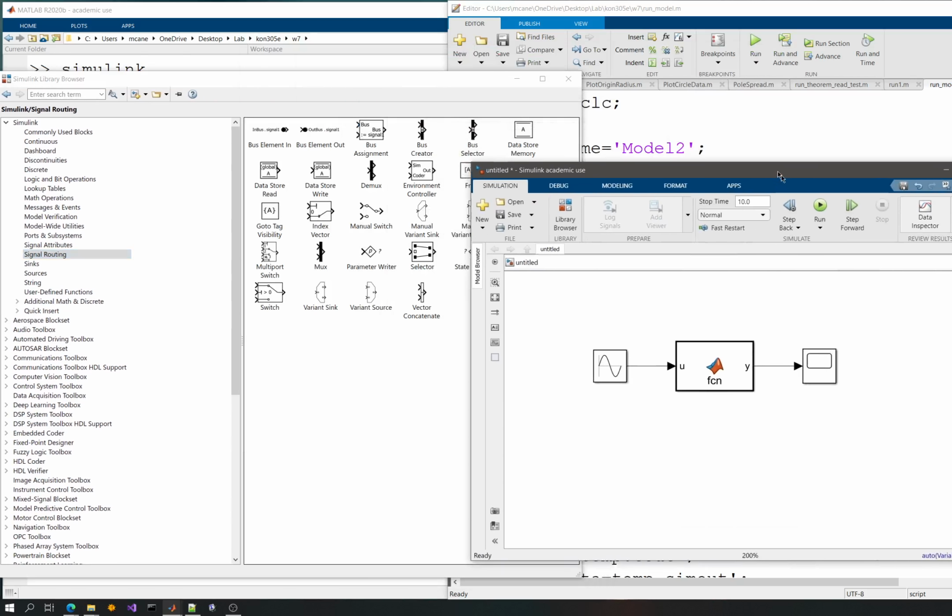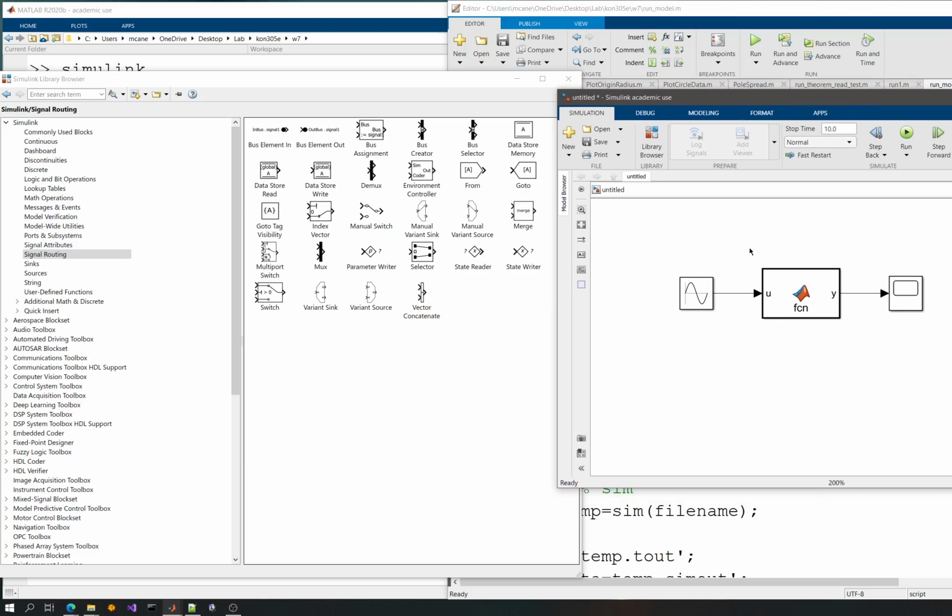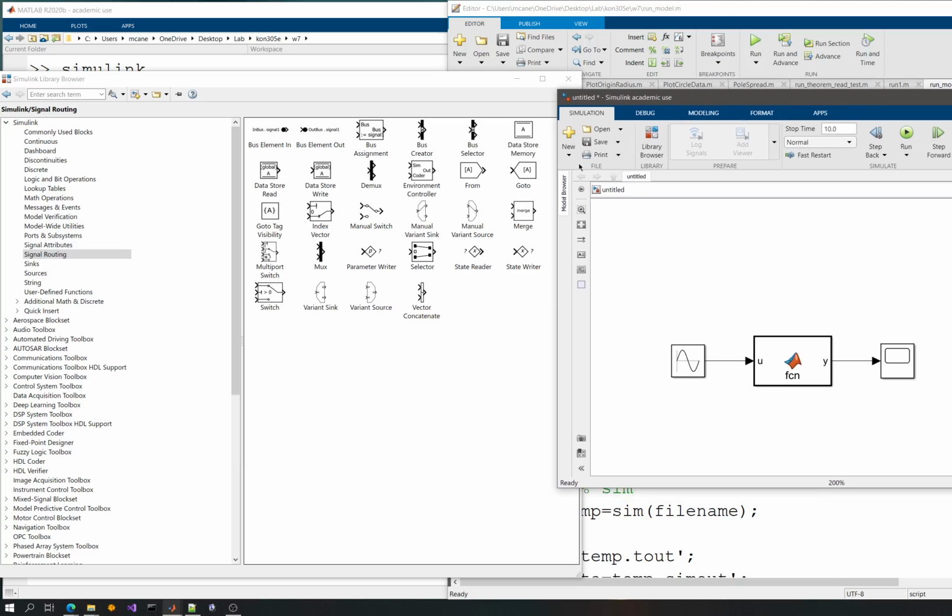So in order to do stuff that has memory in Simulink, that, for example, uses the samples that were used earlier in this Simulink, I have to define a data store memory, and I can read and write to it. That's basically it.